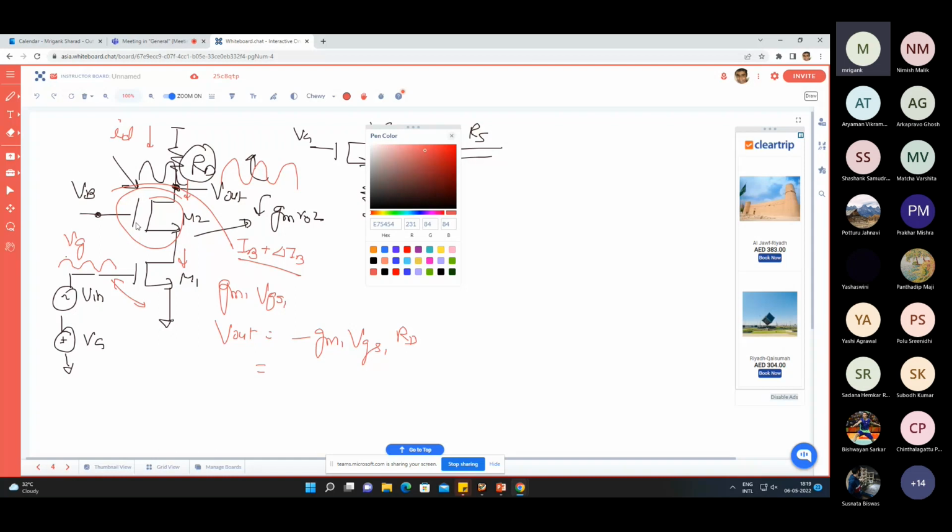So the first thing is, for the output MOSFET, what is the condition? The condition for the output MOSFET will be determined by which voltage? The output means M2. So for M2, which voltage determines the minimum? VB minus VT of M2. Yes, so V out min is solely determined by VB, because if you reduce V out below VB minus VT, M2 will enter into triode. So the gate voltage is VB, and the drain voltage cannot be lower than VB minus VT. Earlier, with the simple common source, it was just VG minus VT. Now what is the condition?